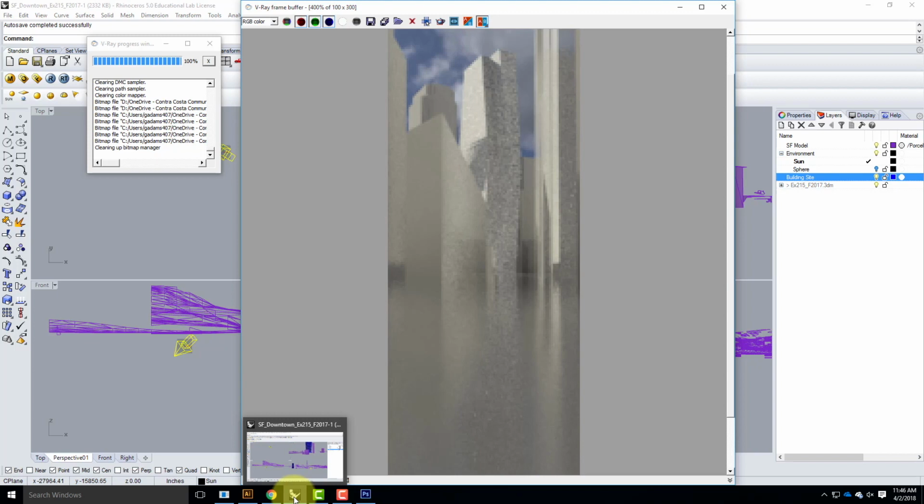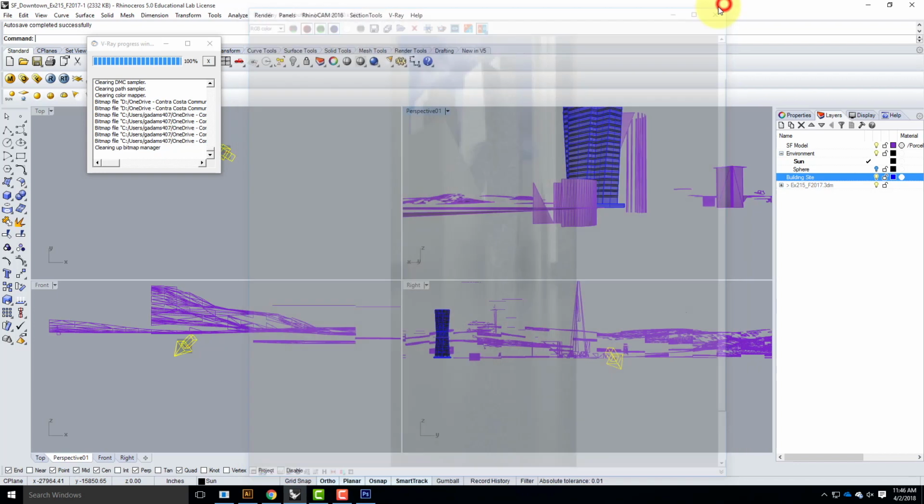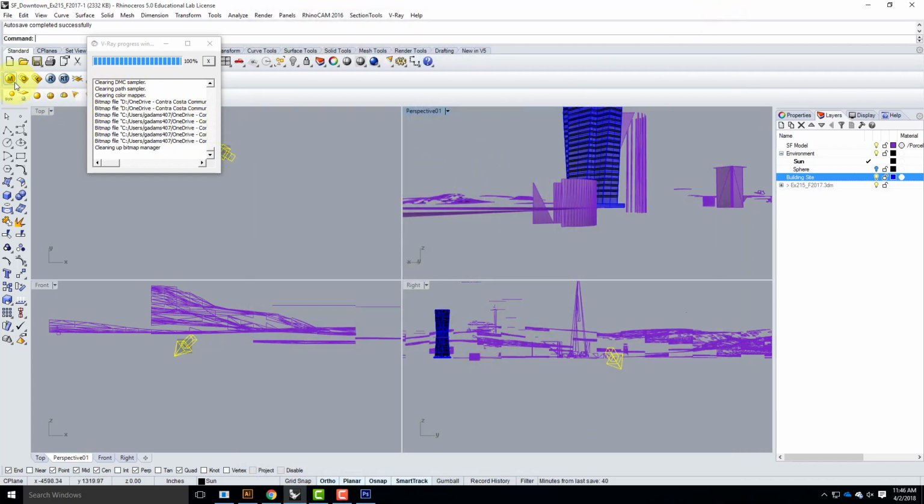The last thing that I'm going to encourage you to do is V-Ray 8.25 will have you turn on some channels in your rendering. It's a little bit premature because you won't be using the channels yet, but these channels are designed to help you, like if you're doing collage work in Photoshop later on, they can really help. So if you turn them on now, it won't impact your renderings at all. V-Ray does all of these anyway, but it allows you to start saving them and getting the habit of saving them.